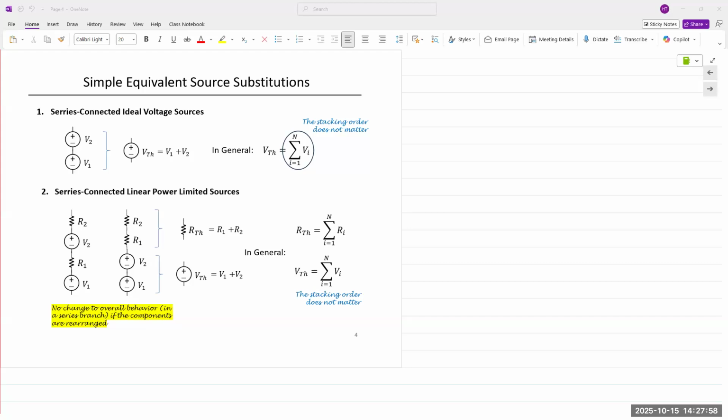The meter now has very low resistance. In voltmeter mode, it has infinite or very large resistance. In current measurement mode, it behaves like a short circuit wire. We don't need to do anything. Simply keep the meter connected between those terminals, change the front panel from voltmeter to ammeter, done. The current measured is your Norton current. No need to change anything.